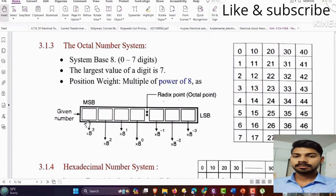So see the integer portion. The same logic we will apply here. The radix point is now called the octal point. The 0th position has the weight 8 raised to 0. The first position has the weight 8 raised to power 1. The second position has the weight 8 raised to 2. And the third position has the weight 8 raised to 3 and so on.